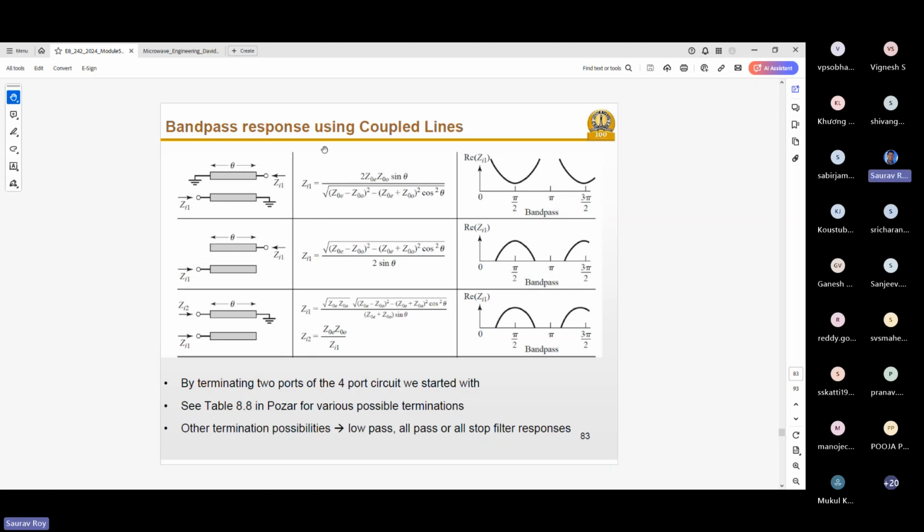You see, just a simple coupled line where the two opposite ends on the other side are shunted, and the other two ends you can connect to your line. Then it behaves like a band pass. That is the first structure. You see, the band pass is in the middle, around pi it passes. On the other two ends there is a null, like a zero. That's why it's a band pass.